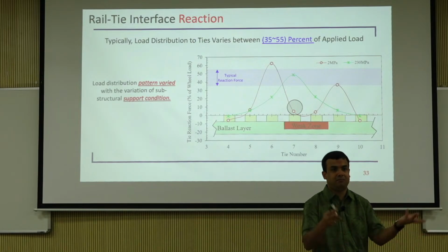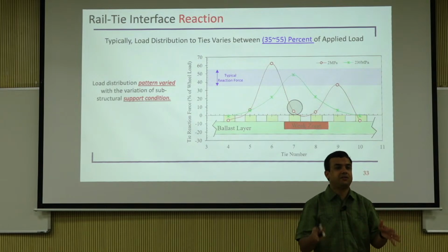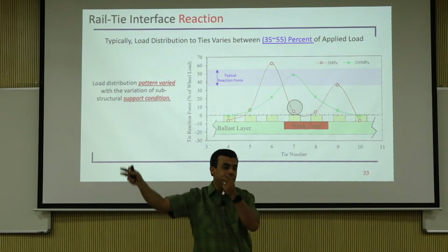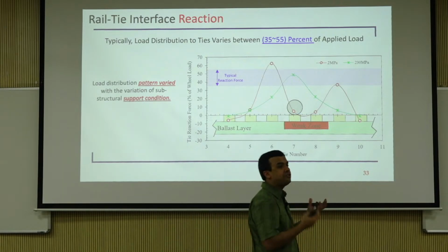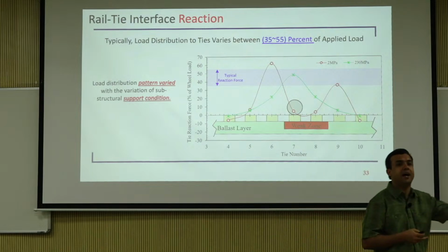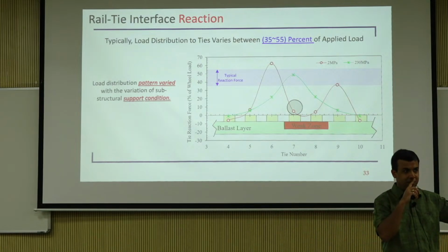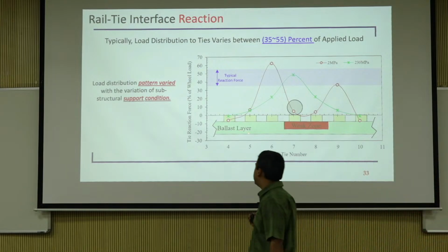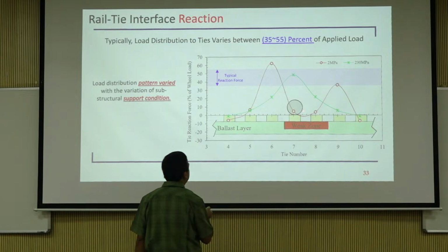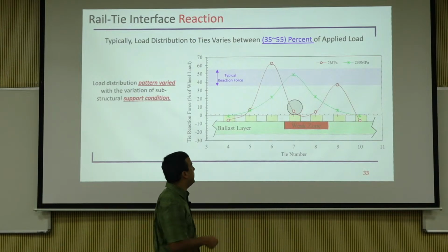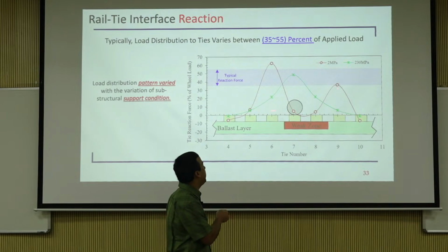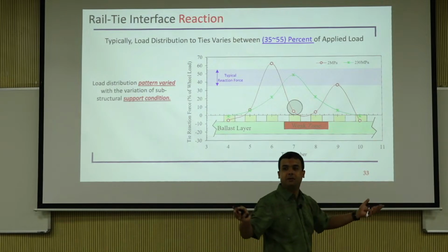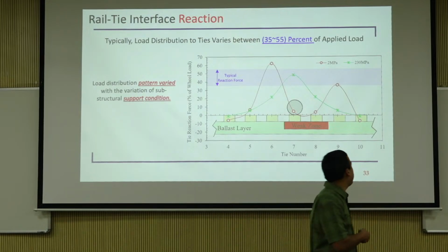The track is there, but the stiffness has changed. You also need to remember that the danger and the loss associated with a track is significantly higher than with a pavement, because we are talking about loss of life immediately, like derailment. So something like this happens, it goes undetected, the load distribution changes, it happens more, then there is a section that is not supported, and you have derailment, right? So how do you track something like this?